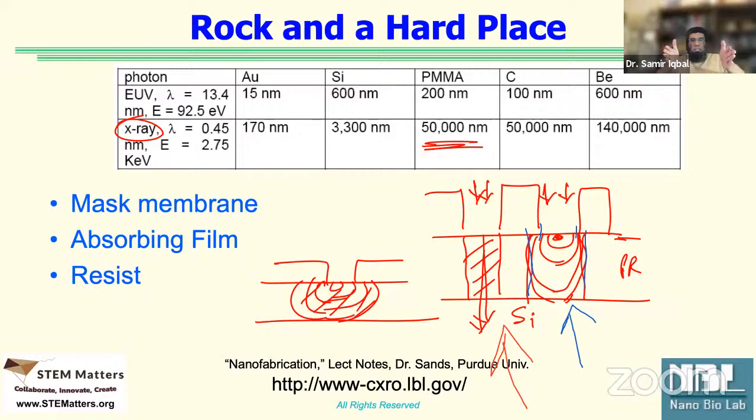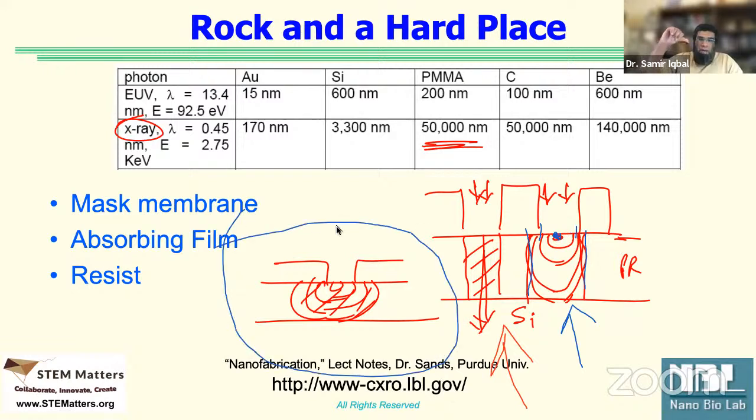What you get is this much because this one, I'm just showing as an example, one interaction, which is supposed to happen here, has resulted in all these waves and caused so many electrons to get flooded. So you get something like this. Bringing my wavelengths down gives me a smaller capability to create smaller feature size, but they carry too much energy. And that becomes a problem to have a resist, right?